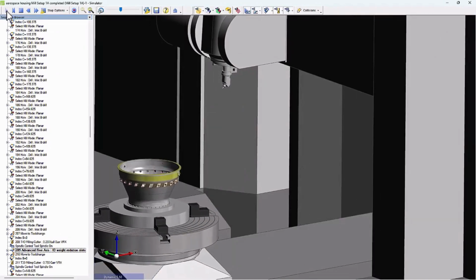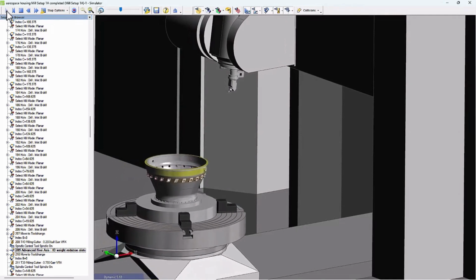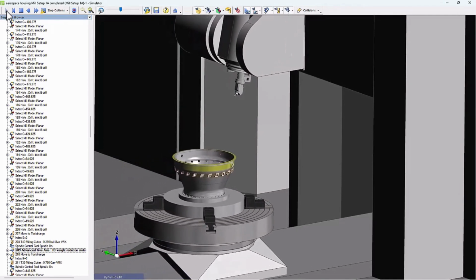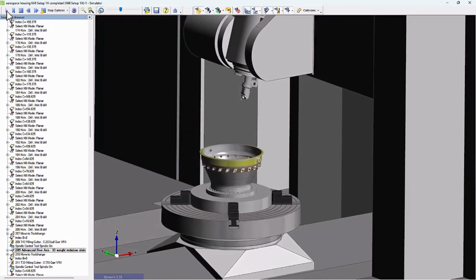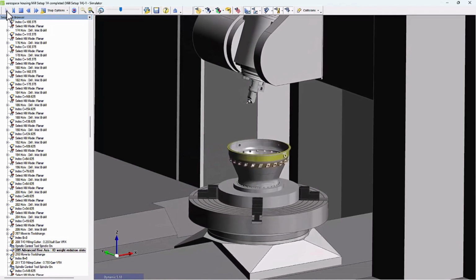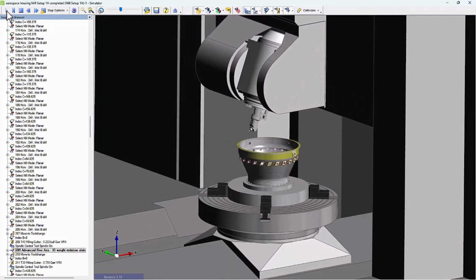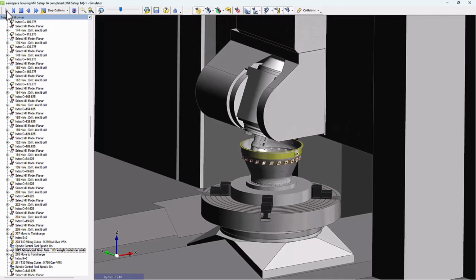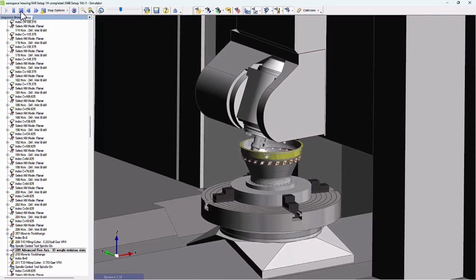We've advanced to a critical stage of the machining process where an angled head is used, and coupled with 5-axis simultaneous milling, we're removing material from inside the part. We trust that simulator's collision checking has ensured that we don't have any collisions with tool and material or interference with holders or anything else, but it still would be nice to see visibly what's happening inside this area. How can we do that?